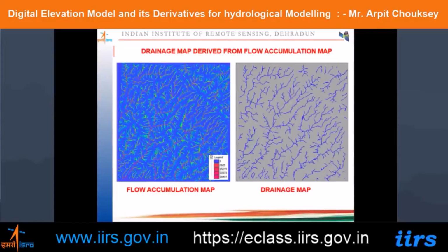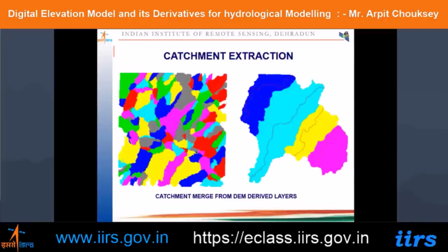In different software like ArcGIS, ILWIS, we can have the option for the illumination sources, and it can be changed also. For example, this is the first picture. It is showing the digital elevation model, and in second part, it is showing the shadow image. So if the illumination direction is kept as the northwestern, that is how the shadow moves, and if we move the illumination direction, the shadow also moves.